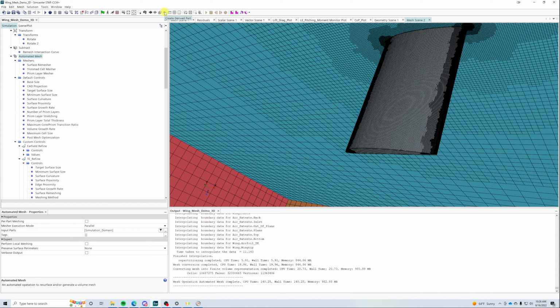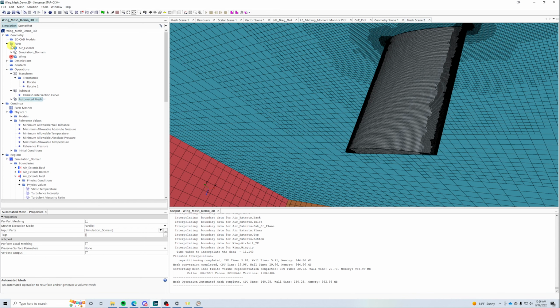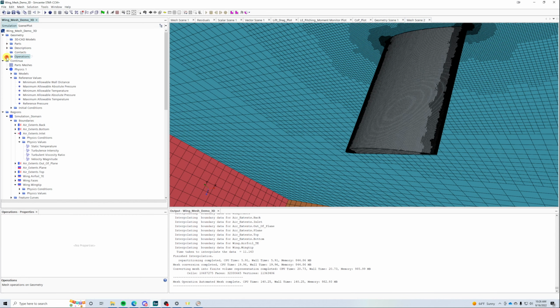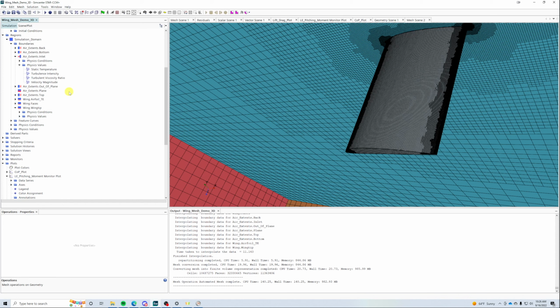We can do this a couple different ways. I'm going to try it this way for a second. If this doesn't work, we'll try a different way. This is using what is known as a derived part. This isn't anything actually physical. This is just a kind of theoretical part that you're using to do something that doesn't affect the physics or the mesh. It is derived from existing geometry. So, what we're going to do is create a planar section, a planar cut.